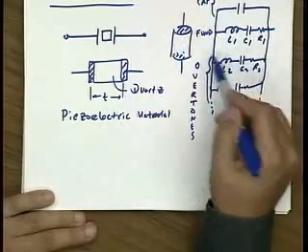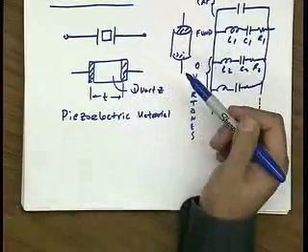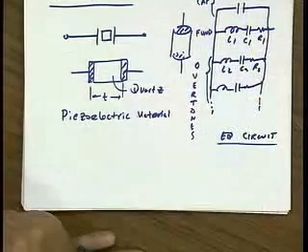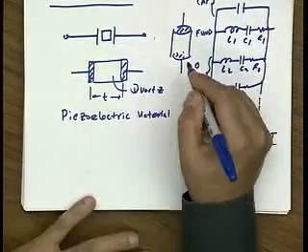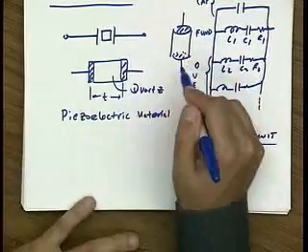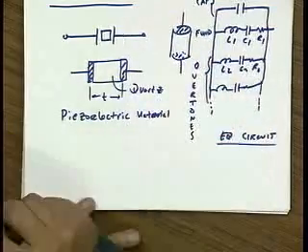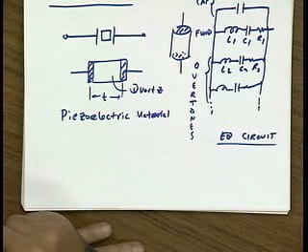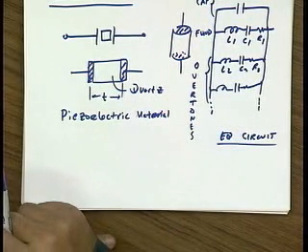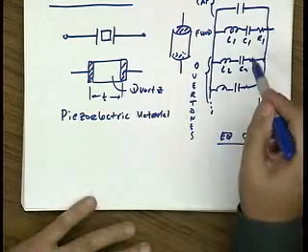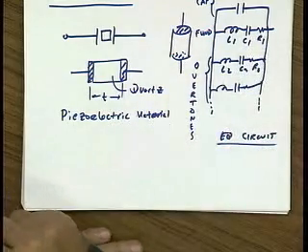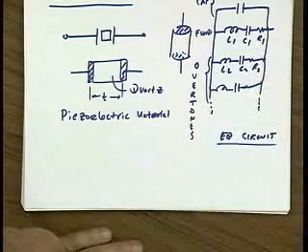And in fact, there's a good reason why this model works. It actually goes back to some fundamental theory. From an electrical perspective, this is a two-port device, and it has some frequency-dependent impedance. It turns out that you can model any arbitrary impedance with an equivalent circuit that looks like this, where these catch the resonant modes of your circuit. Okay, so this is an equivalent circuit.